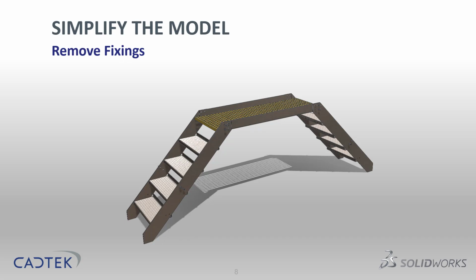Now all this design is held together by lots of nuts and bolts. However, we know that they're not going to fail because they're basically in shear. But if we add those into our design, that's going to take everything a bit slower. So what we can do is delete those out and then we'll apply those as boundary conditions in the next step.